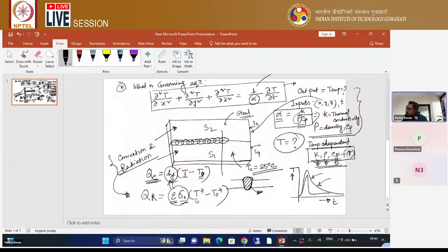To incorporate this weld bead geometry, while the heat source is moving, the heat source generally takes a shape that looks like a double ellipse, a teardrop shape. This is your electrode central line; once it has a speed v, a velocity, it takes a teardrop type of shape. That I have already told you. So that's why, once you divide these